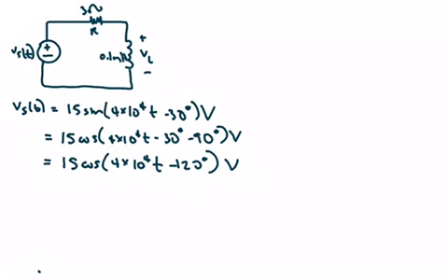Now we know in order to turn this into the frequency or phasor domain that all we have to do is use that amplitude there and our phase shift, phi. All right, so now that we have our input signal as a phasor, we need to pay attention to putting our resistance and our inductor into its equivalent impedance.